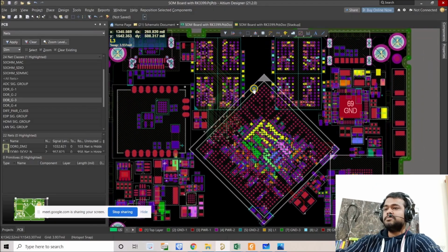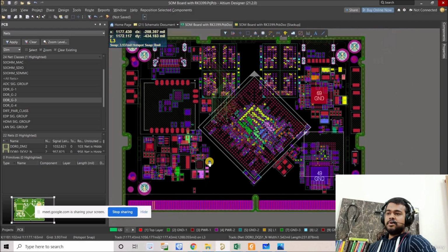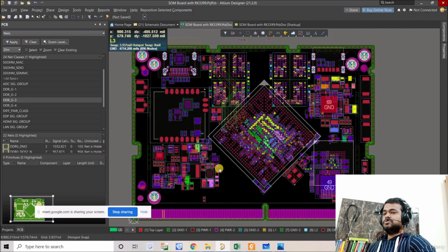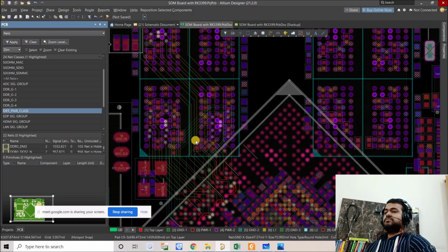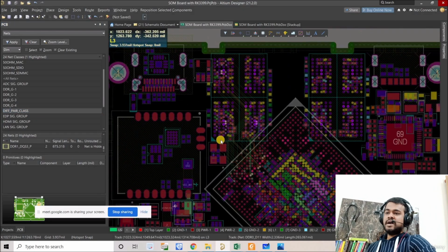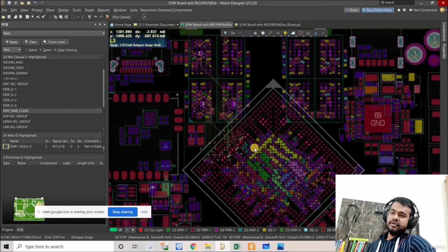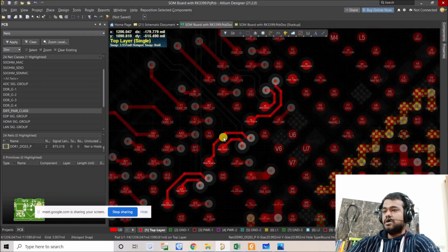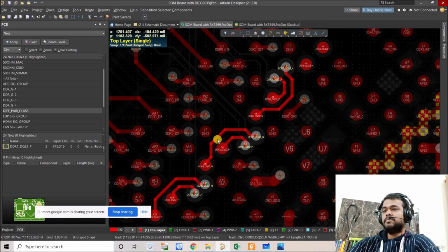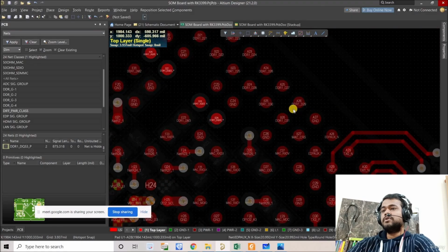So instead of doing that, I'm just going to give you a few instructions, like what are the things that you have to complete on your own, and that is your assignment number 9, right? To do that, again, the first thing, before starting anything, you have to add this differential pair class on all of the differential tracks, right? So for example, if you see on this one, right? We faced this problem, right? You will face the same problem for this one, for all the